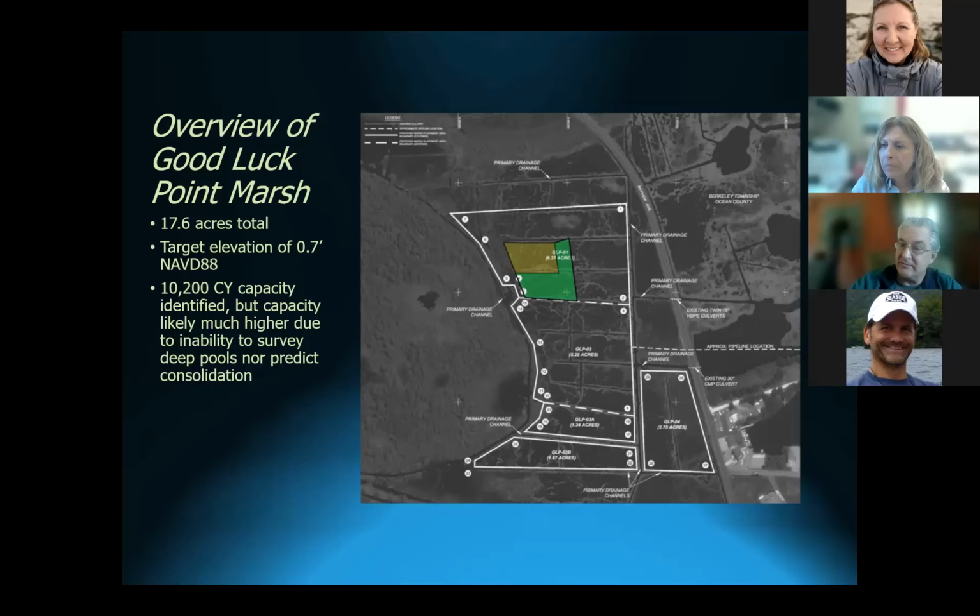Now, I realize that nobody wants to bury the existing marsh, neither do we. However, putting a couple of inches over 37 acres or 47 acres or whatever is practically impossible to do. So what we need to do is to come up with a practical solution that would allow us to place material and take advantage of the site and its characteristics, such that the material would actually go onto the site and stay on the site. And we needed enough capacity to make the project work, but also have the type of materials that would flow easily onto the site. All of that had to be evaluated.